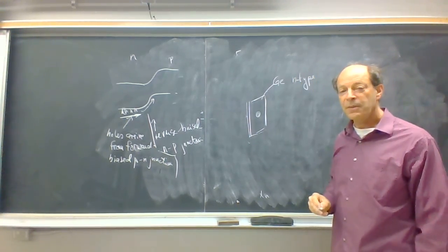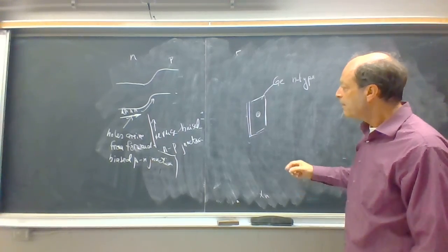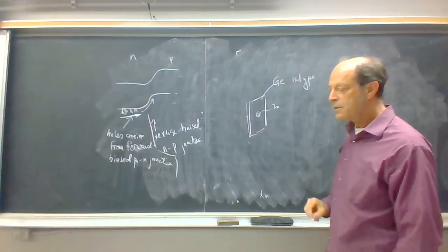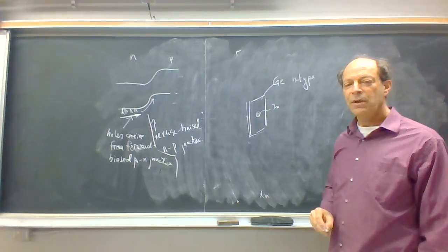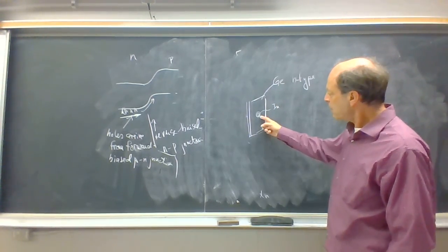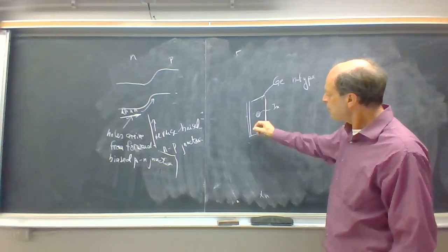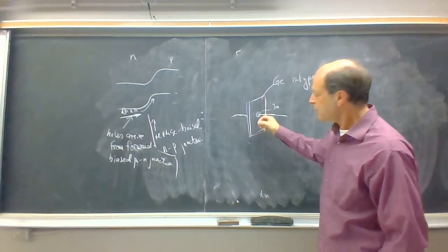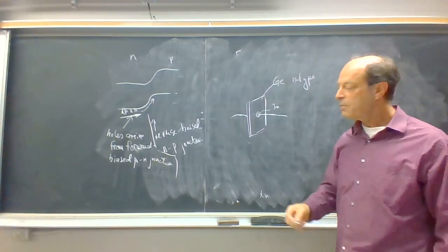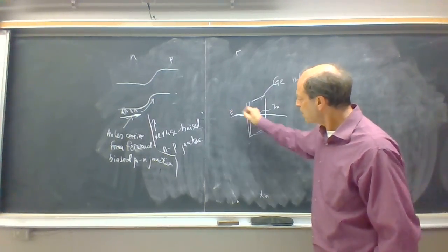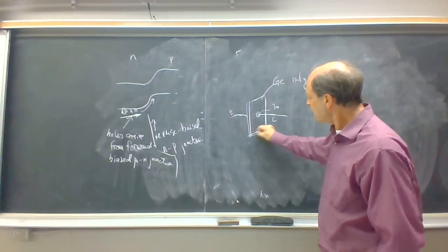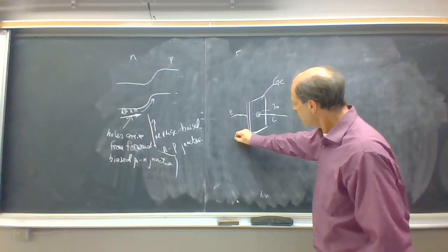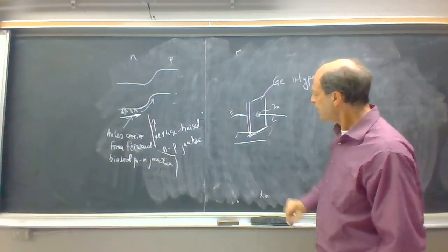So in order to create the collector and the emitter, they put a blob of indium, which is a group 3 metal, on one side, and another blob of indium on the other side. And they connected 2 wires to those 2 blobs of indium to form the emitter and the collector. And this material, the germanium slab, was connected to a platform to hold the whole thing up.